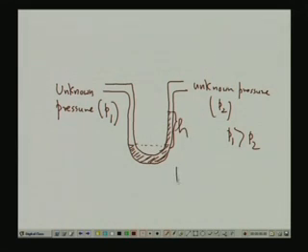So again, P1 minus P2, the pressure, is equal to h d g, as before. h is the height of the difference of the columns in the manometer, d is the density of the manometric liquid, and g is the acceleration due to gravity. Now, the typical or cheap manometric liquid I should say is water, easily available, and you can use distilled water which will be clean.